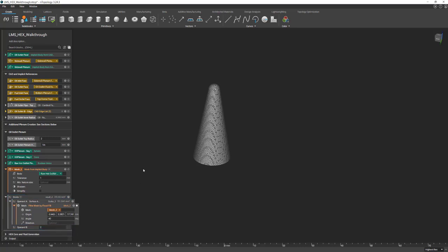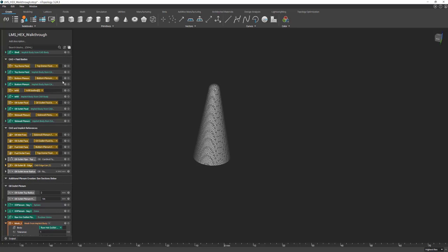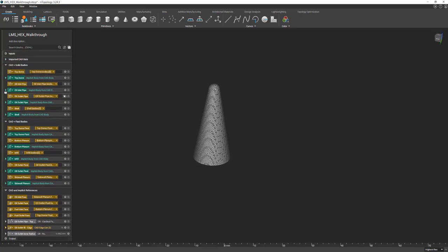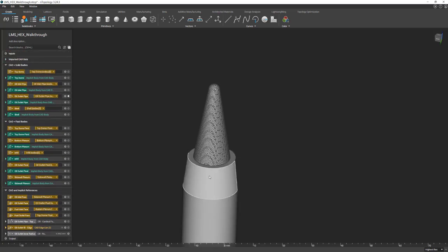I'm putting an operand of 2 because half of this area, at least, is going to be consumed by the baffles that we create to keep the fluids from mixing. So as long as this exit surface area is greater than or equal to the flow area that's coming out of the outlet pipe, then I'm good.